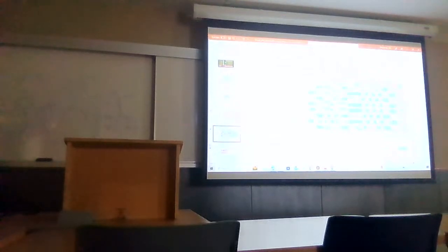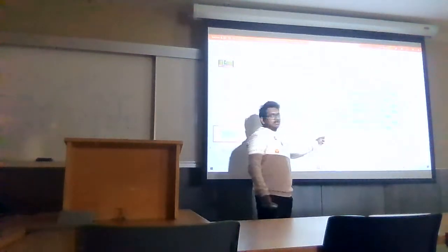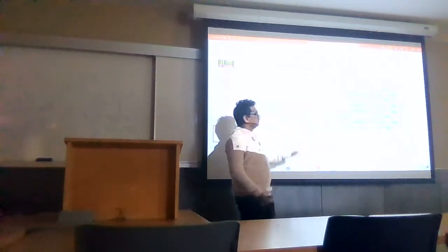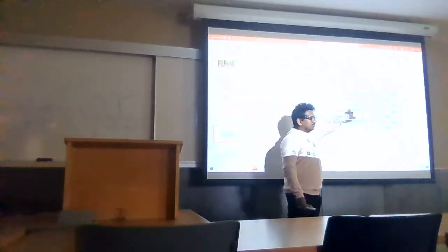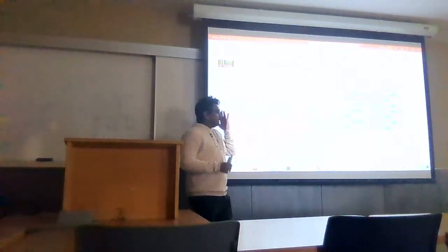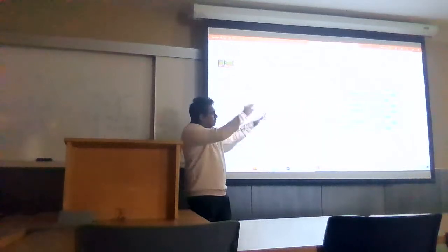Yeah, this is also some current mirror matching. It's really weird, but you can see there is 0% mismatch. This mismatch means whatever the tool is doing, it assumes a center in this block, and from the center it measures some x and y distance, and it should be the same.